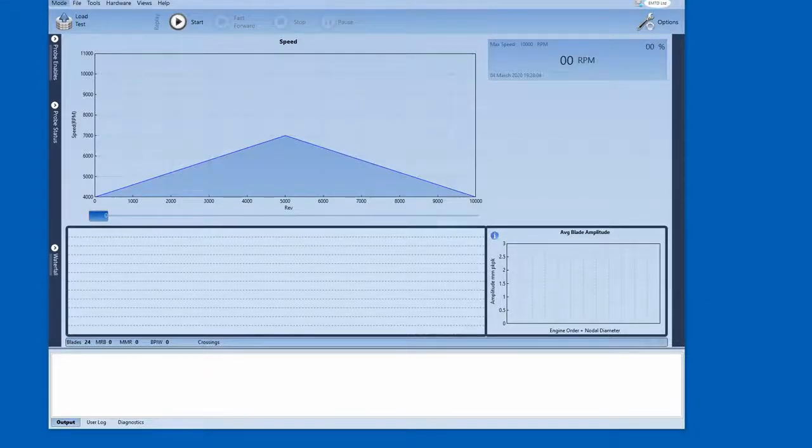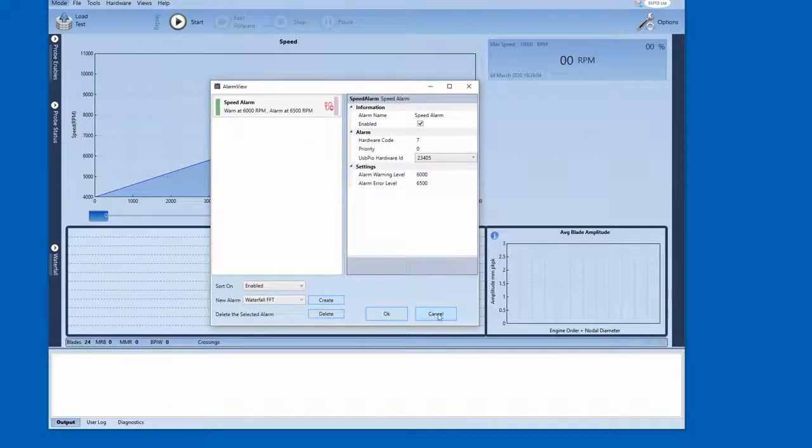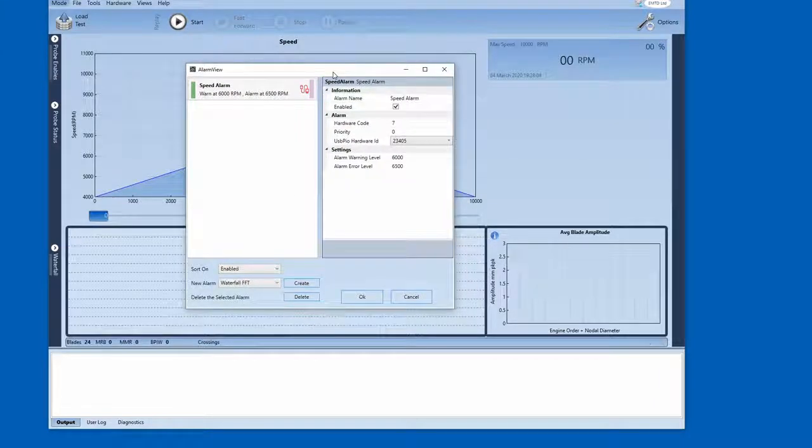And one last comment for those of you watching this in the future is that there's a slight bugette that has gone unnoticed: when you cancel out of the alarms panel using the cancel key, it will reset the speed warning levels. If you click OK, so if you go in, change nothing, click OK, you're fine. But if you press cancel, these get reset, and version 4.0.1 onwards has that fixed. Just a warning.